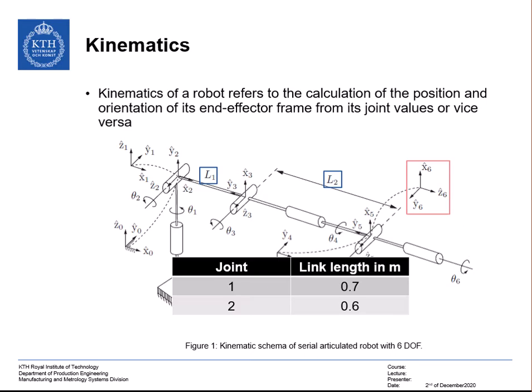To catch a tennis racket out of the air, one probably needs to know these with values down to millimeter accuracy. But how accurately does one have to know these parameters to put a spot weld in the body in white of a passenger car, or drill a hole into the fuselage of an aeroplane? The answer is, as accurately as possible, which in commercial applications corresponds to 1/10 of micrometers. The process to find these parameters is called industrial manipulator calibration.